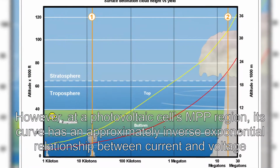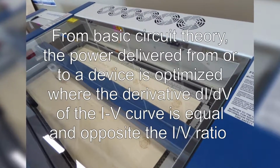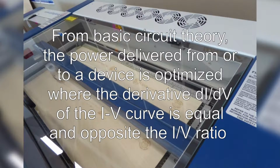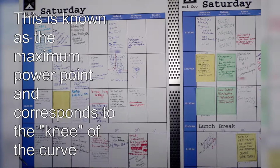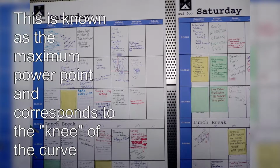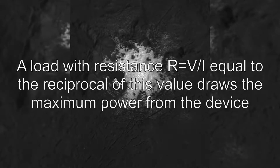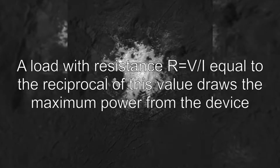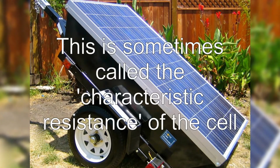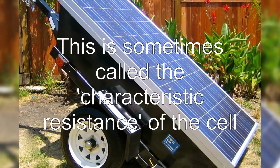For any given set of operational conditions, cells have a single operating point where the values of the current and voltage of the cell result in a maximum power output. These values correspond to a particular load resistance, which is equal to V/I as specified by Ohm's law. The power P is given by P = V × I. A photovoltaic cell, for the majority of its useful curve, acts as a constant current source. However, at a photovoltaic cell's MPP region, its curve has an approximately inverse exponential relationship between current and voltage.